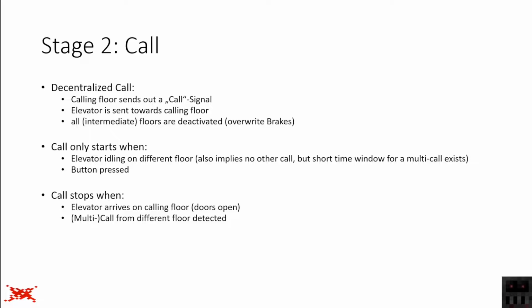And a second condition is if a multi-call is detected. Now, a multi-call is a rather dangerous situation with the setup I'm going for here, because a multi-call is essentially if you activate a call on different floors at pretty much the same time. There is a small time window where you can make multiple calls. And if that happens, due to the fact that all floors are deactivated except for the calling floor, that ends up with all floors, without exception, being deactivated.